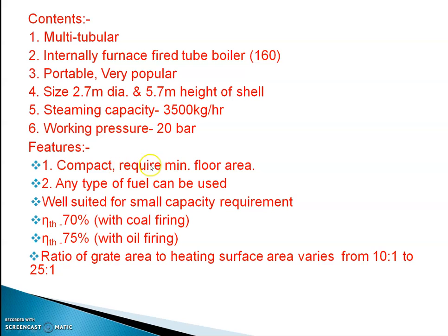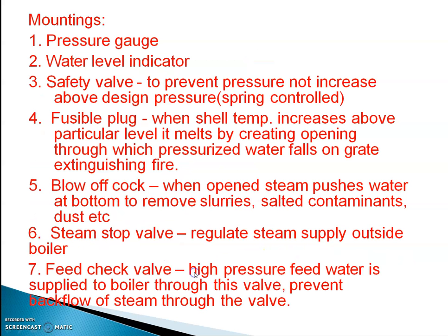It is very compact and requires minimum floor area. Any type of fuel can be used, and it is well suited for small capacity requirements. The thermal efficiency is 70% with coal firing and 75% with oil firing. The ratio of grate area to heating surface area varies from 10:1 to 25:1.